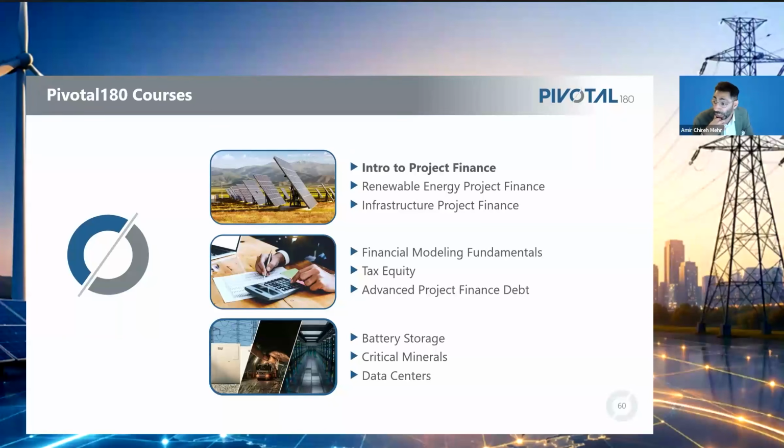So one of the questions is, what is the difference between the balancing authorities and the 10 RTOs? There really isn't. It's just a different nomenclature used for the same thing. But you could think of there are balancing authorities that aren't RTOs. All RTOs manage balancing, but you may have more regionalized balancing authorities in some context as well. That's probably the best way to think about it. But one of the functions of the regional transmission organizations is to manage the balancing services.